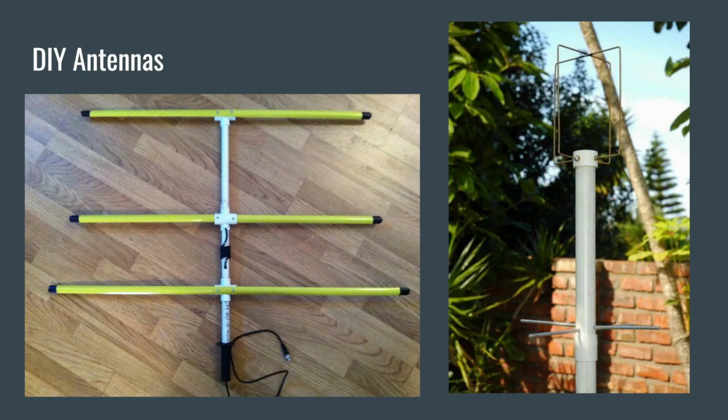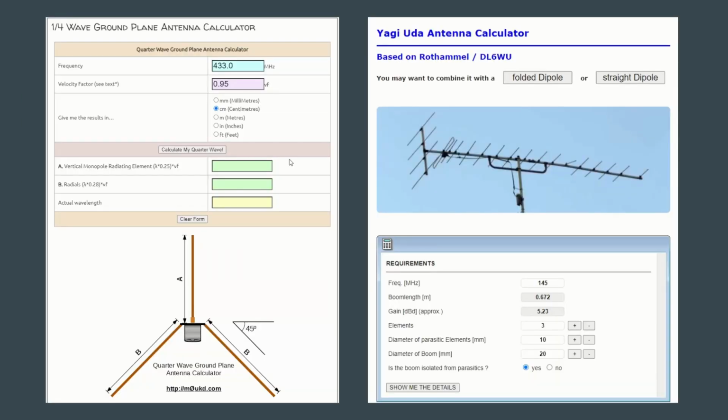You can also use various lengths of copper, aluminium to make your antenna. The dimensions of the antenna depend a lot on which frequencies the satellite you want to receive from. There are various online calculators available that will give you the dimensions on how you need to assemble your antenna. For information on the frequencies the satellite transmits on, I refer you back again to the SatNOGS database where we got our tracking information from, as it will also show which transmitters are active on the satellite including their frequency. This is pretty much the simplest setup you can put together to get started. But while this sounds simple, you can have great results.